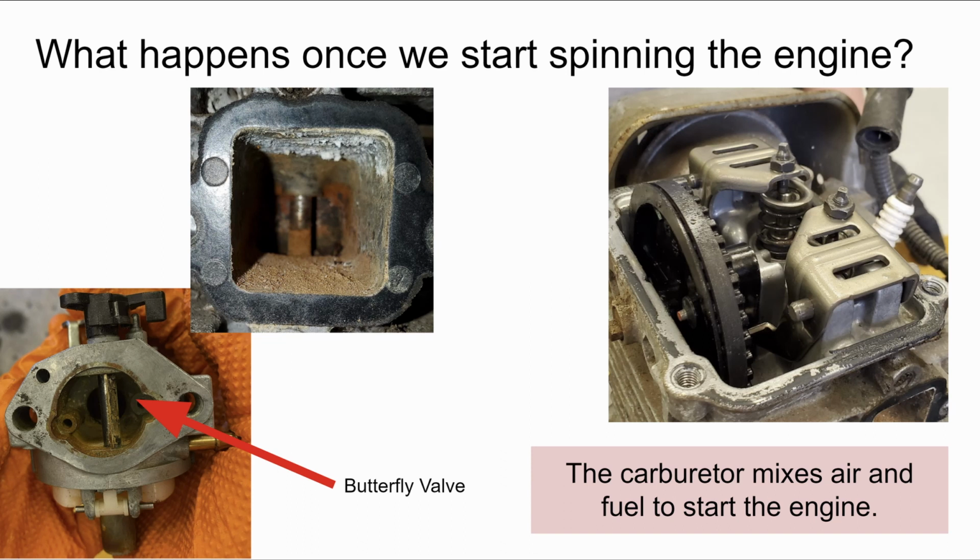A carburetor is a device used to mix air and fuel at the correct proportion needed to make our engine run. It utilizes a venturi to generate a pressure difference that sucks up fuel into an airstream that is sent to the intake manifold. A venturi generates a pressure difference by constricting fluid flow through a narrow region, causing the fluid speed to increase and the pressure to decrease through a smaller area.